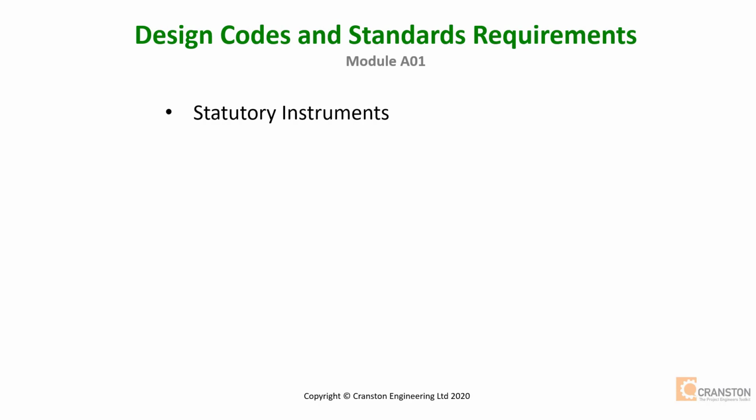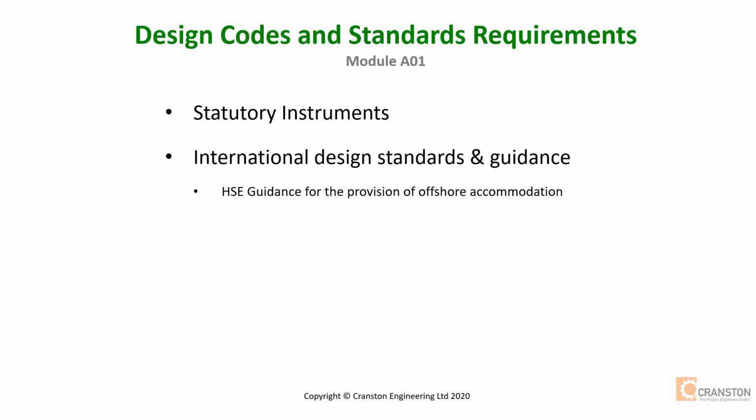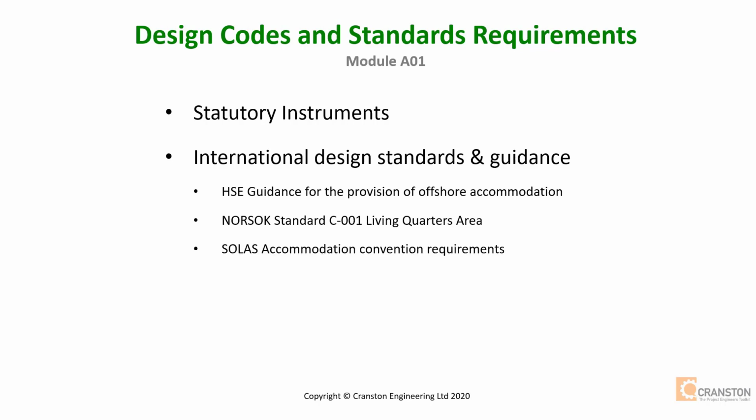While this will vary by jurisdiction, the following key documents can be referenced for information: International Standards and Guidance, the UK HSE Guidance for Provision of Offshore Accommodation, NORSOK Standard C-001 for living quarters, SOLAS Safety of Life at Sea Accommodation Convention requirements, and finally DNV 2.7-2 Certification for Offshore Accommodation Containers.